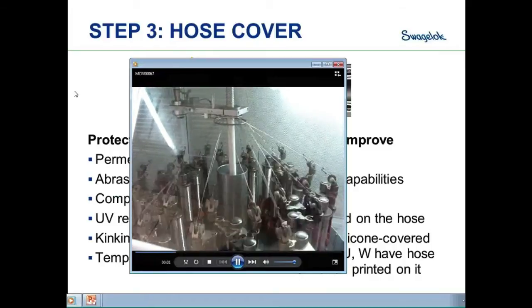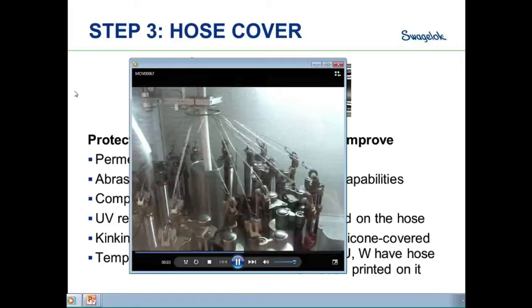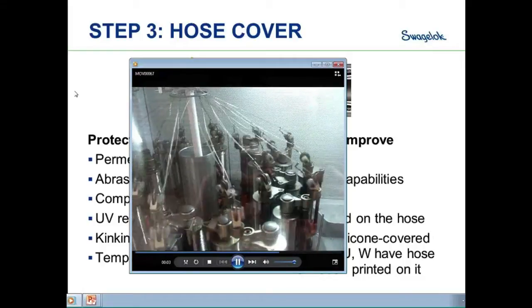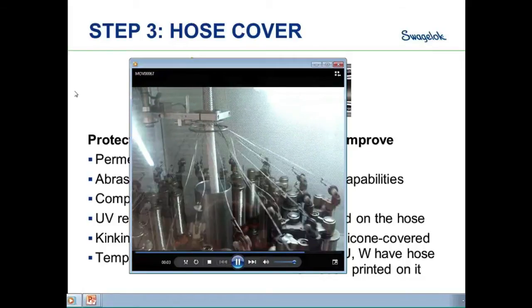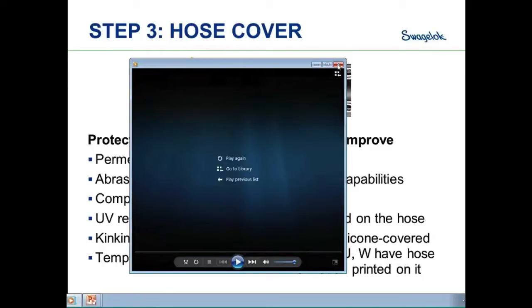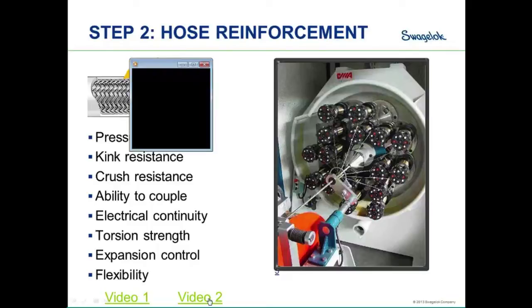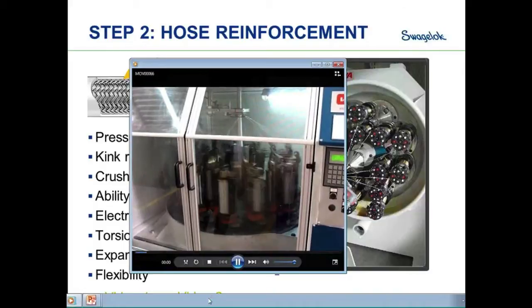So this is a slow motion. If you look, the carriers or the bobbins are dancing in and out of each other, 2 over, 2 under, okay? This is a very controlled process. There's the angle, the tension, all of that comes into play. And as a result, the tension of the braid, the angle that it's coming down, will control what type of flexibility characteristics you have. Now we're going to look at that in real speed.